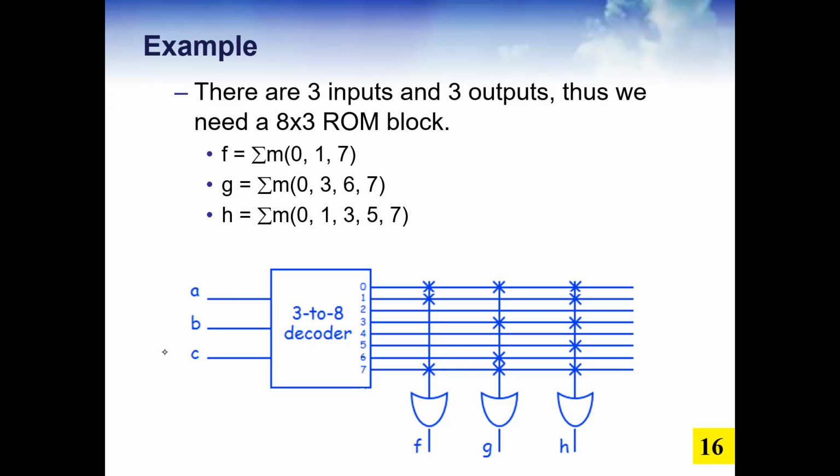But guys, don't use this array logic symbol in the design of chapter number 4. You must use the conventional symbol design. This array logic, you can use only for chapter 7 related questions like ROM design and all, because it is specifically for the ROM design, for the memory concept. It's not for chapter number 4, the combinational circuit design. Don't use it there. So if it is coming to ROM design, then you can use a single line and cross connections. Otherwise, don't use it with chapter number 4.